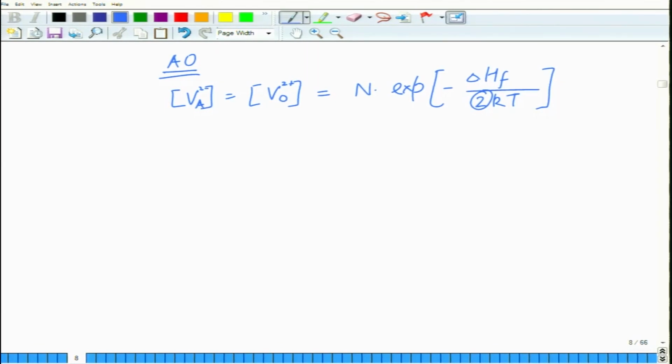So this is about the point defects discussion, that you have point defects such as vacancies and interstitials, and point defects are basically stable defects, they are equilibrium defects, and free energy is minimum at a certain concentration at a given temperature, and their concentration increases as a function of temperature. So as you increase the temperature, they become more in number exponentially, okay.